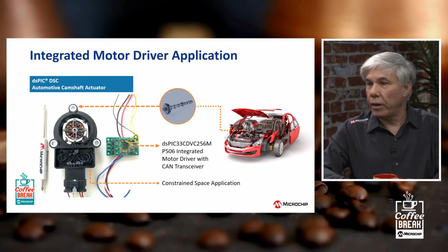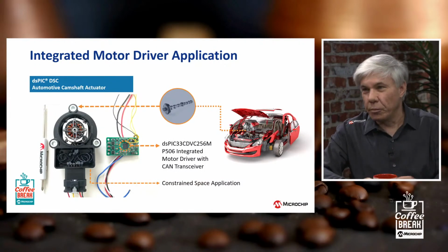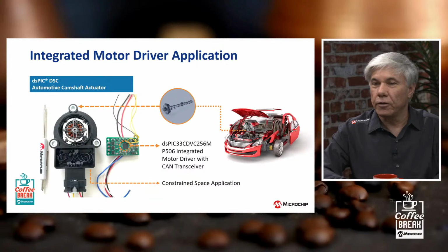And so the space for that electric motor is very small, and the space for the control board for that electric motor is even smaller. And so here you can see that this little rectangular space is very small, and they really only have room for the 6 MOSFETs and an integrated type of motor driver in order to solve the problem.